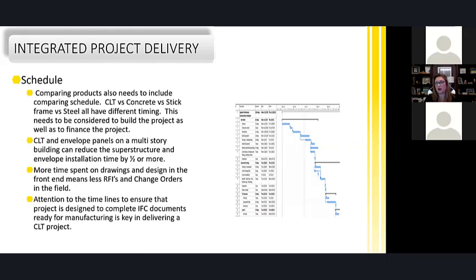And then we're talking now about panelized concrete cores, because we were running into huge thickness issues making a CLT core. And we need to marry that up with steel in the event that we wanted to go higher than 10 stories. After all the work on it, we realized it wasn't impossible to do a concrete panelized version, and it really works very well with the CLT.